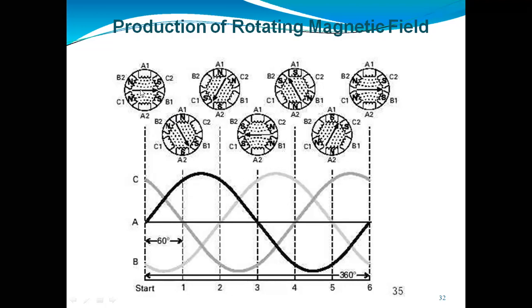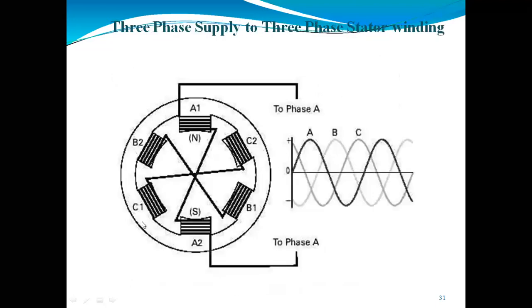So here when you are drawing the first diagram, for A, after that what are we saying? We are saying B phase is starting after the 120-degree phase difference. After that C is starting, again there will be the 120 phase difference between B and C. And if you are taking from A, there will be the 240 phase difference.